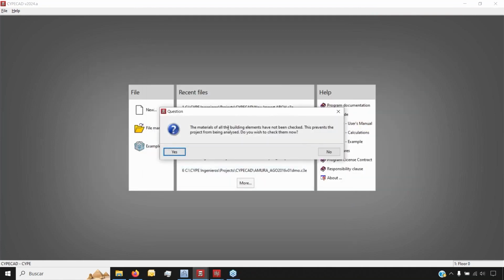And of course, just like we did before with construction materials, we are going to import walls that will be linked to these elements that can add rigidity to the model in case of seismic analysis, as well as import the line loads that will be applied as dead loads according to the kind of facade that we're working with.